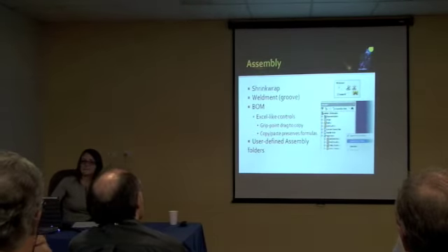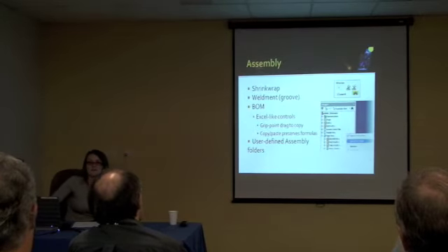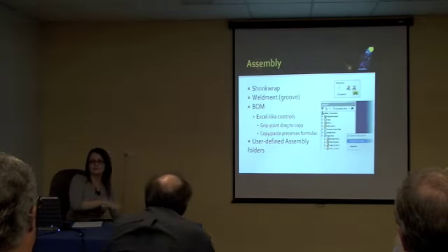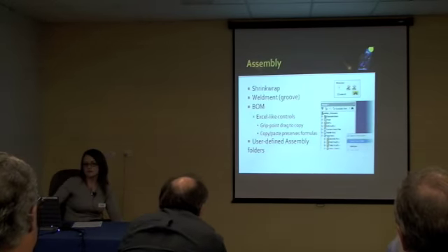Does it carry through to the BOM? No, it doesn't. It's irrelevant to the BOM. It's just a way to organize your browser. If you wanted it to carry through into the BOM, you would have to go through the demotion process. But this is literally just a way to organize your browser so you don't have like 1,000 parts in your browser. Okay?